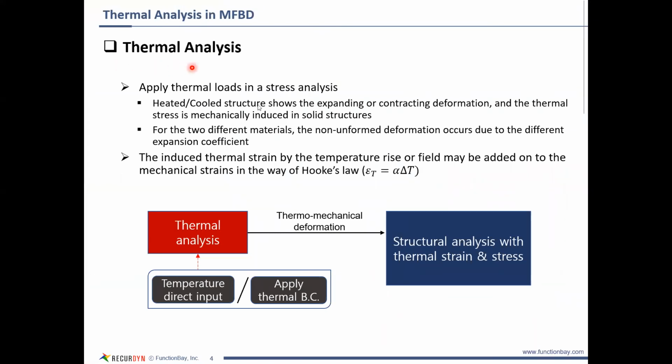To start off, thermal loads are now an option within Flux. What you can do is apply thermal boundary conditions to a flexible body, and then that conduction will transmit through the material, and you end up with thermal strains that occur because of that. We'll look at some graphical representations of that. Basically, you'll see the material begin to expand or contract based on the conduction happening within the material.